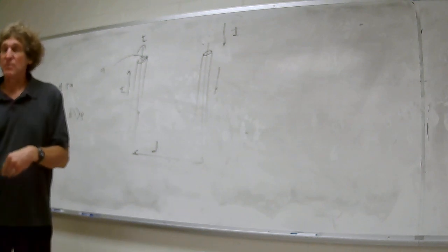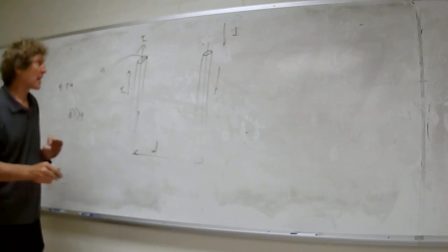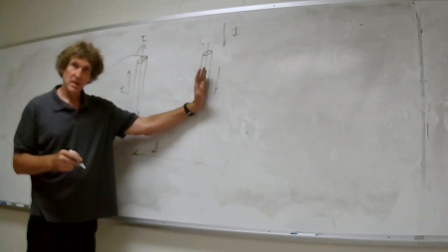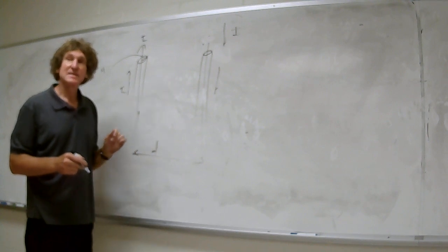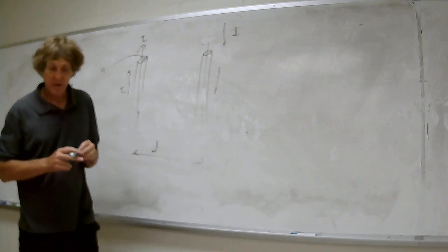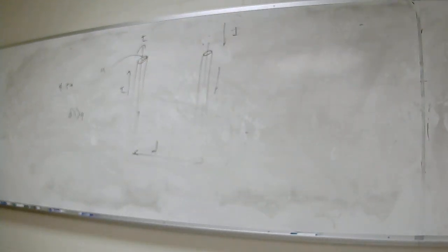This is standard. When you're calculating the inductance of a wire, there's two things to worry about. There's the internal inductance of each wire per meter. Then there's how much inductance is in here. I'm going to show you a trick to do this. Now remember, we could do it with energy. Energy is a pain in the butt with this one. We go nuts. Dual flux. I think he does energy for this one.